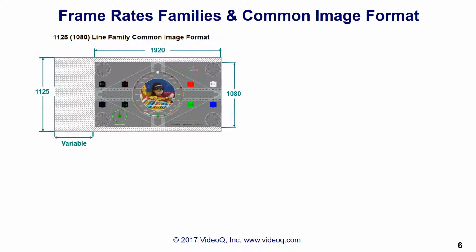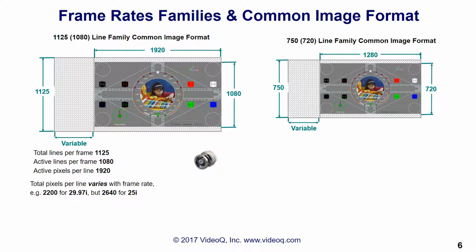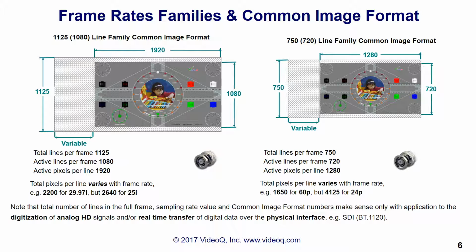Using the same sampling rate for several quite different scanning standards is possible only because the samples are packed in accordance with the common image format sampling structure. Common image format numbers make sense only with application to the digitization of analog HD signals and/or real-time transfer of digital data over the physical interface, meaning SDI. For file-based operations, only active image data are relevant, and sampling rate value has no meaning.